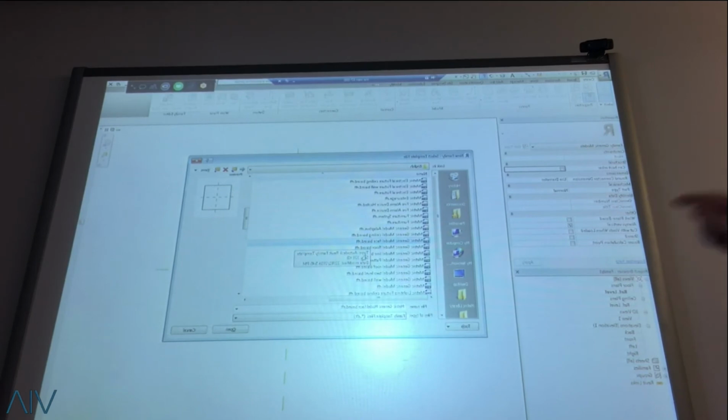Okay, because what happened is that generic model is only going to host on a level, or if you specify that object to a level, that's fine. But once you want it to be on any surface, for instance, let's say you want a light to host on a ceiling, a wall, or a floor, then you use what's known as the face base. You could use floor and other stuff, but I like the face base because it could be anything. It could be ceiling, floor, roof, or walls.